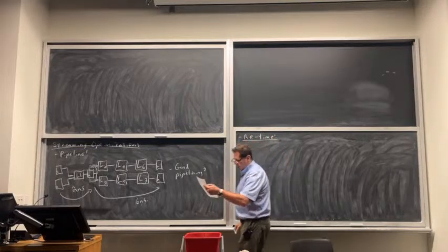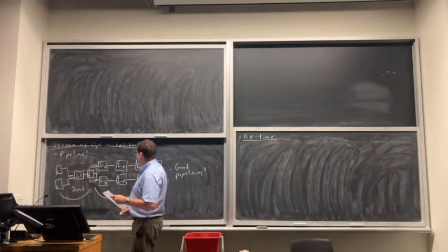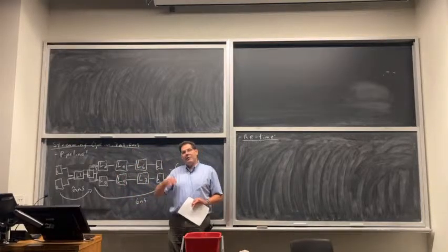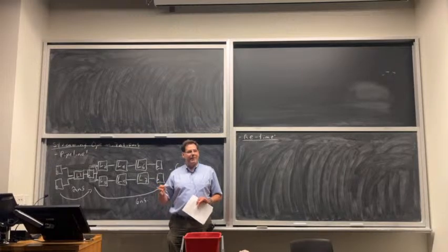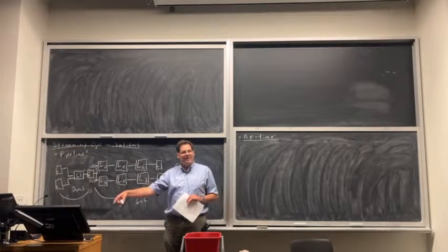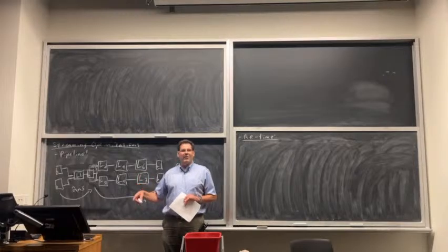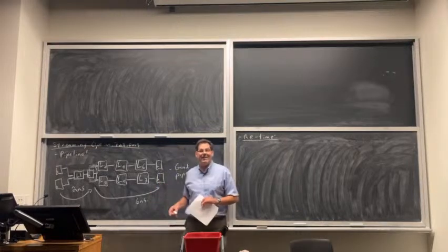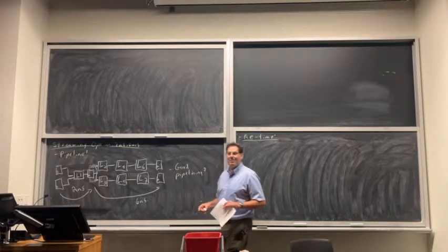Okay, so retiming is nice, and it works well with pipelining. So again, in general, you have to put the pipeline registers in. There's no box you can tick to tell the CAD tool, well, like Lab 1, we gave you a functioning design, but we didn't pipeline it. There's no box in Quartus you can tick where you say, pipeline it for me, right? Which would be great. If you had that box, you'd be like, that was the easiest assignment ever, right? I just had to find this box. There is a box you can tick that says retime.